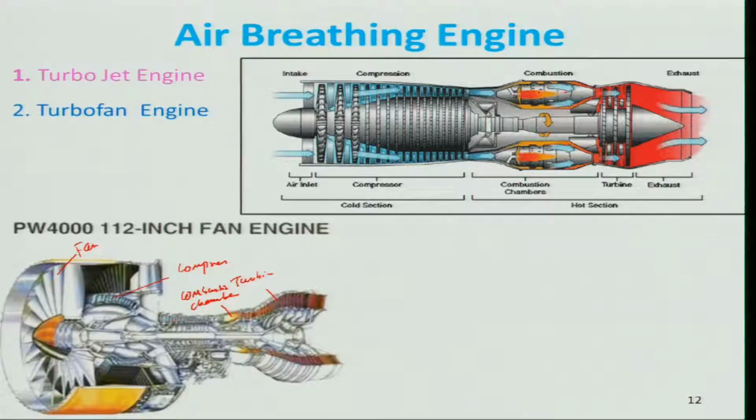So, the total pressure will remain almost constant, but it will be a little bit lower, because the objective is to decrease the change in total pressure in the compressor and the turbine. In the turbine, of course, what will happen to the total pressure? It will be lowering down, because you will extract the work out of it.